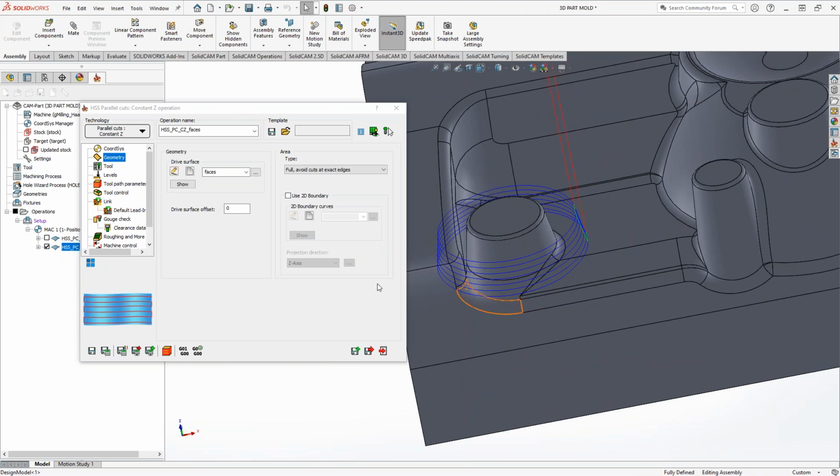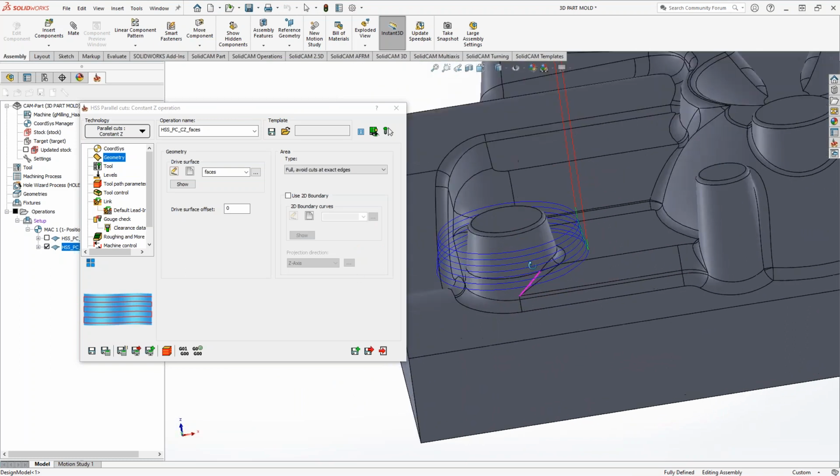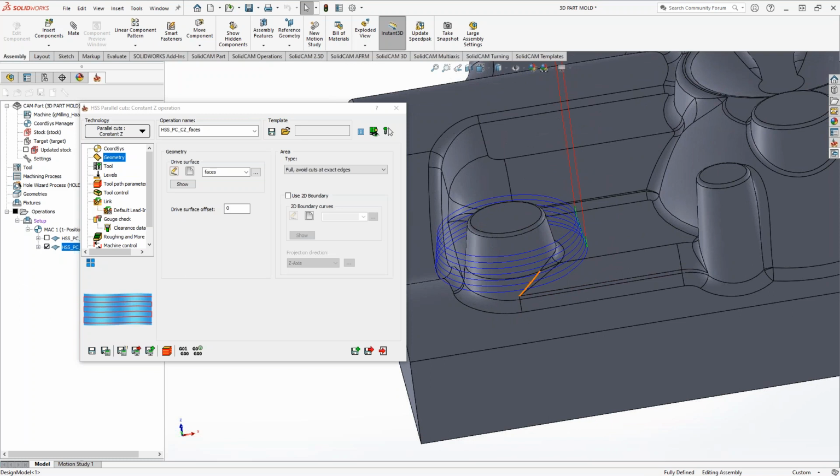And you can use split line not just in this one direction as a planar, but you could actually get it to split any direction, any edge that you like to make the geometry a little simpler. This is more for surfacing, but some of the HSS, HSM, HSR, 3D machining, anything that you want to kind of limit the travel of the tool using the surface, split line is a real easy way to get edges.